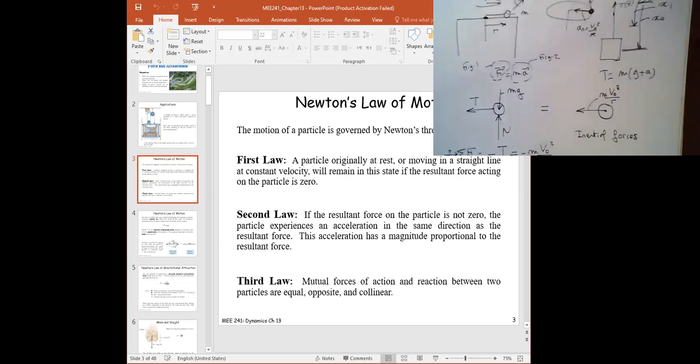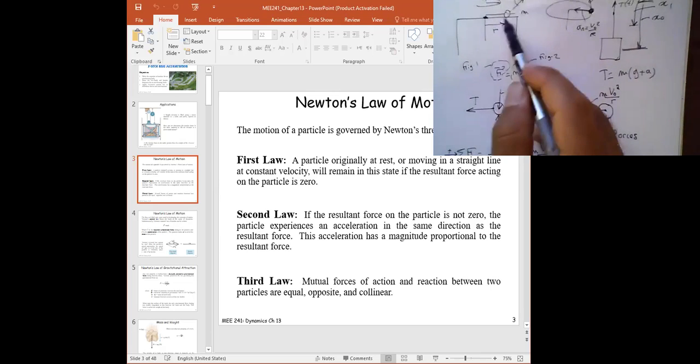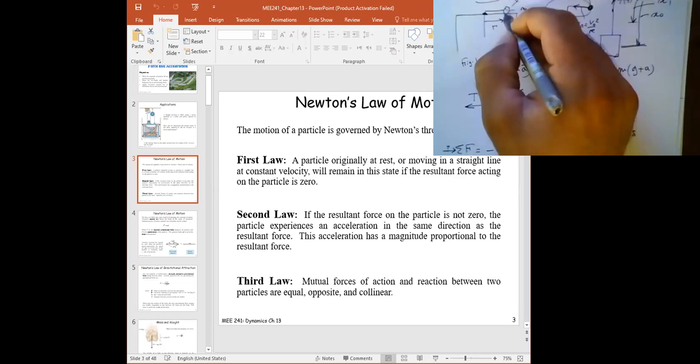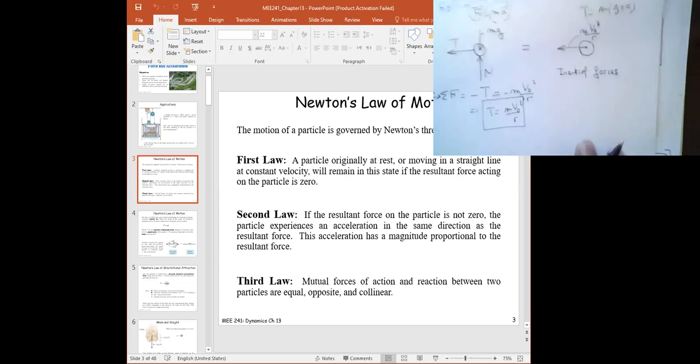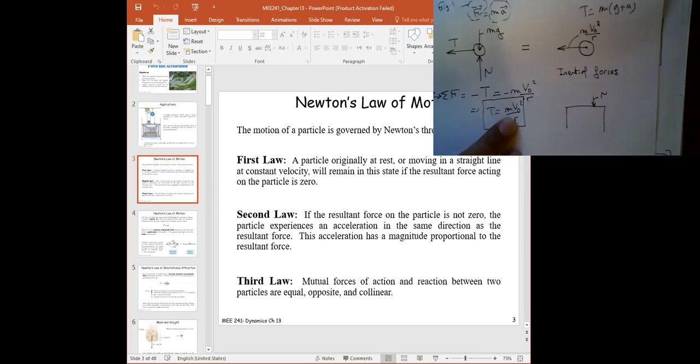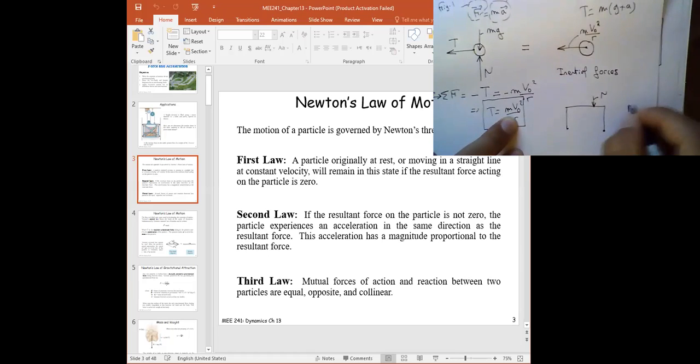So here, in the case of this guy, the force between the sphere and the table is equal and opposite, right? So if I was going to do a free body diagram on a table, what do I get? I'm going to put N on the table. Whatever I have the ball, I'm going to put N on it, and then I'm going to put mg of the table. What are the other forces that I have on a table? Can someone tell me? Let's say the table has the weight of m.